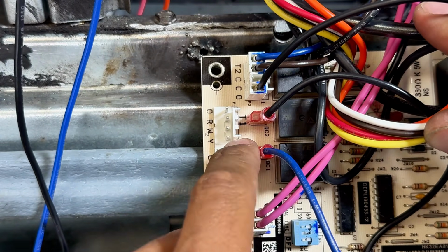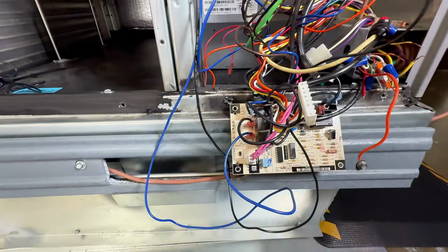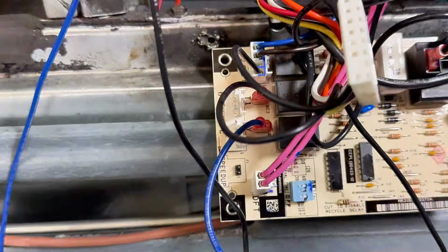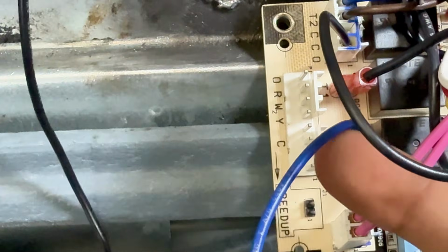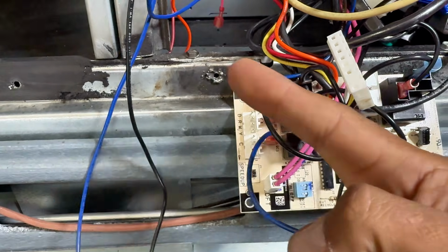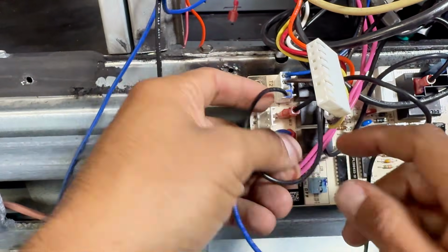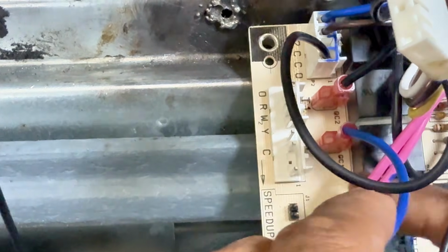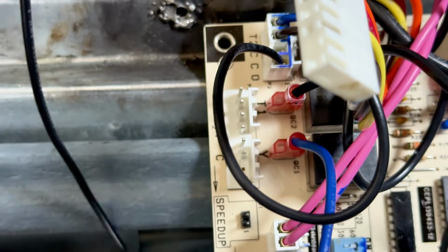We got Y, T1, okay? Y and T1. What are these? These go to my pressure switches. So this blue one here, let's see. So the way it works, once the Y, right, comes here, it sends 24 volts out through this one. And then if my pressure switches are closed, it comes back on my black wire. Let's confirm that, okay? So let's go ahead and take this Y1 here, okay? So that Y1, and then it has to come back. So it's just one long wire going through switches coming back, okay?